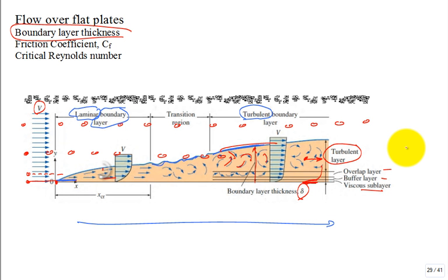All right. So what is this boundary layer thickness? You can define it in the laminar region, transition region, turbulent region. It's where the velocity at that distance going out is 99% of the free stream velocity. So if it's slowed down to 98, 95, 90, 70% of the free stream velocity, you're in the boundary layer. But if it's 99% of the free stream, guess what? Basically, you're out beyond the boundary layer. That's the definition of the boundary layer. Why didn't they define it as 98%? I don't know. Why not 99.9%? I don't know. The consensus is it's 99%. I'm sure the first people that studied it said our instruments can't really measure anything less than 1%. So there you go.